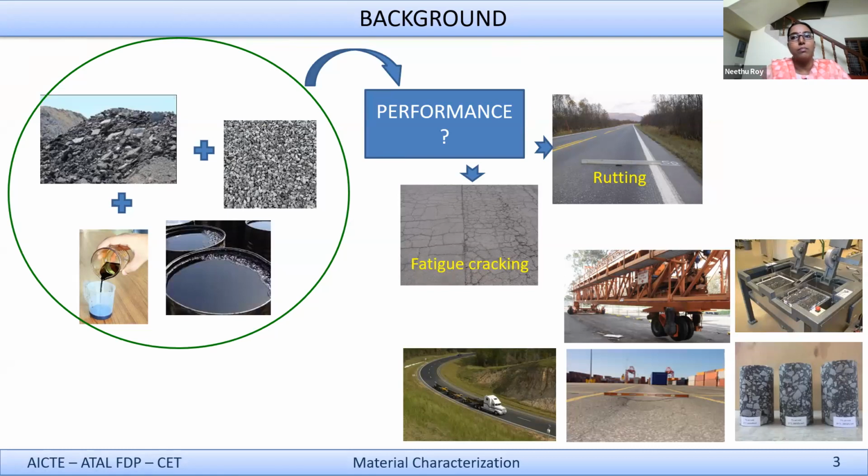You are looking at majorly three aspects. One is rutting, second is fatigue cracking, and the third one is low temperature cracking. As far as a country like India is concerned, we are not very much concerned about low temperature cracking. So the major distresses that we will be concerned about are rutting and fatigue cracking.